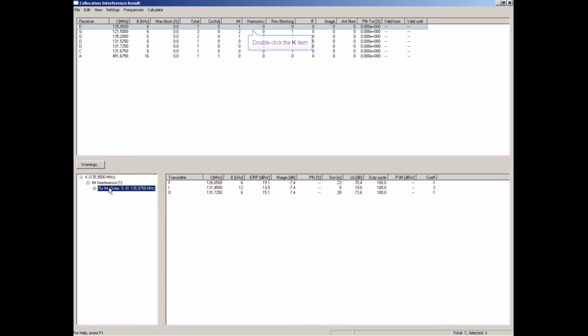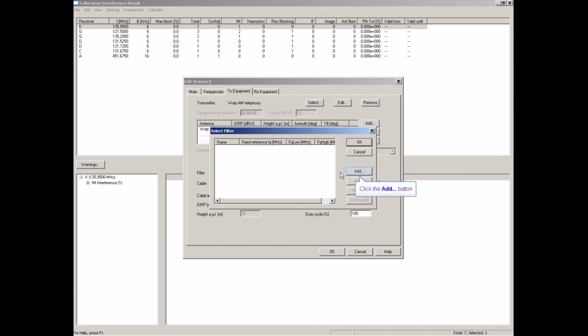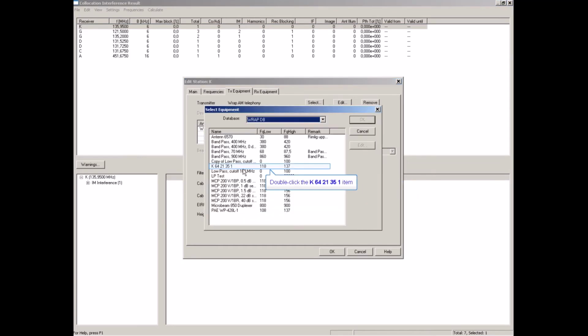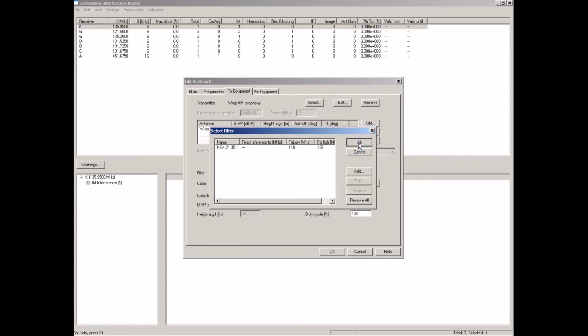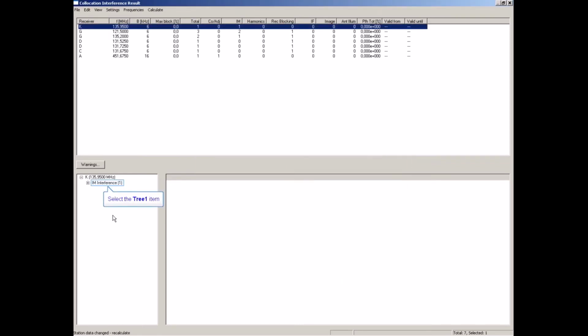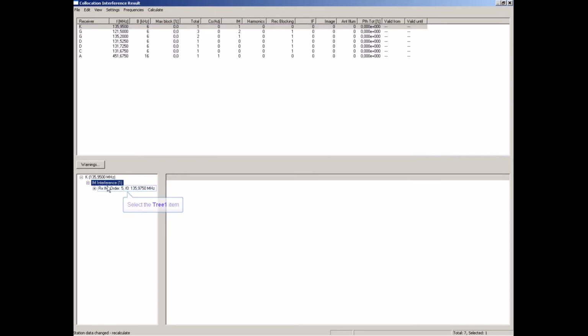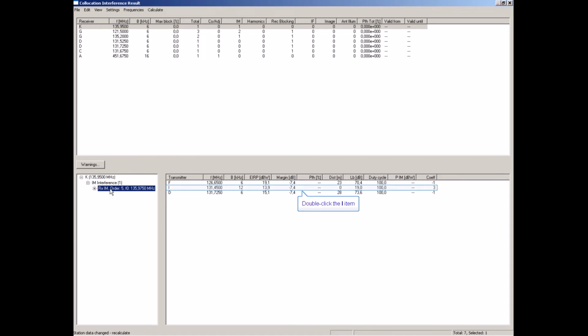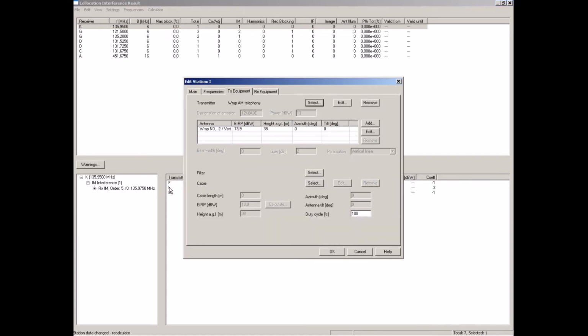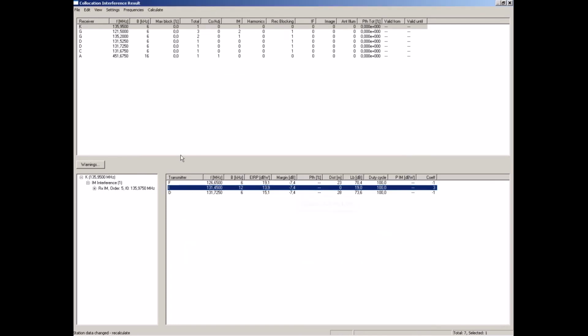Receiver K. Okay, let's put filter on it. It is right on top of transmitter I, 0 meter separation. So let's fix the antenna. Let's just move it a little. Usually not much difference in antenna height is required in order to fix a situation like this.